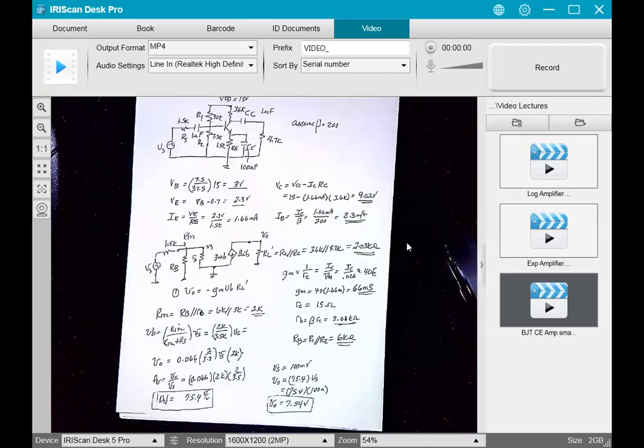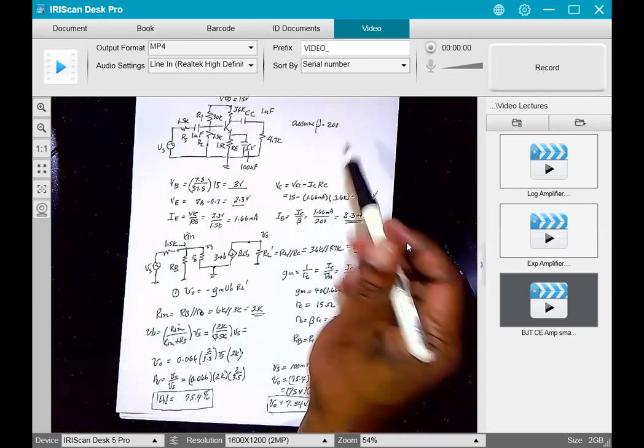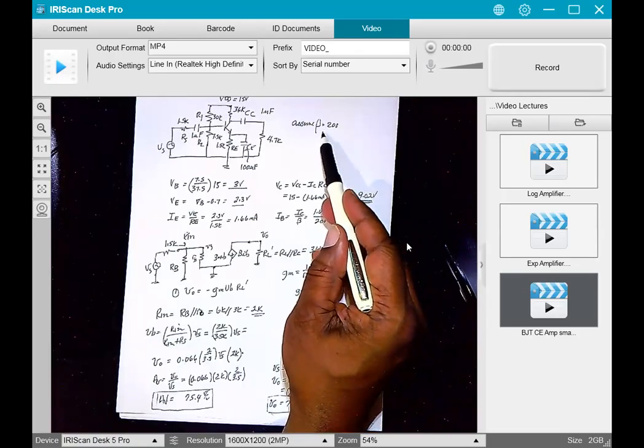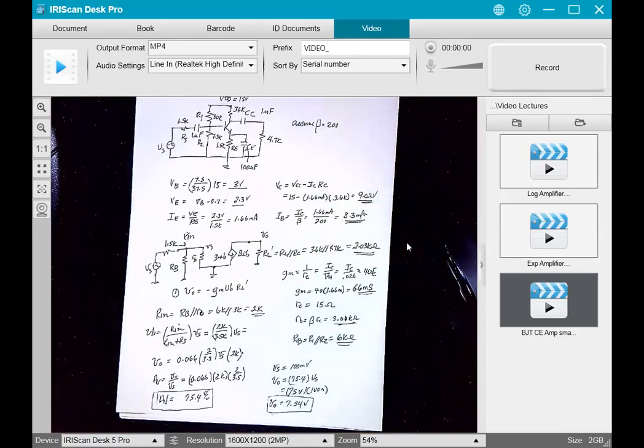Okay. What did you say that beta was, Mr. Bells? I see the RE was 15. What was beta? 200. Okay, 200. And again, I normally would not just write the answer. I would normally write the equation, substitute in the 200 and the 15, and then say equals 3K.